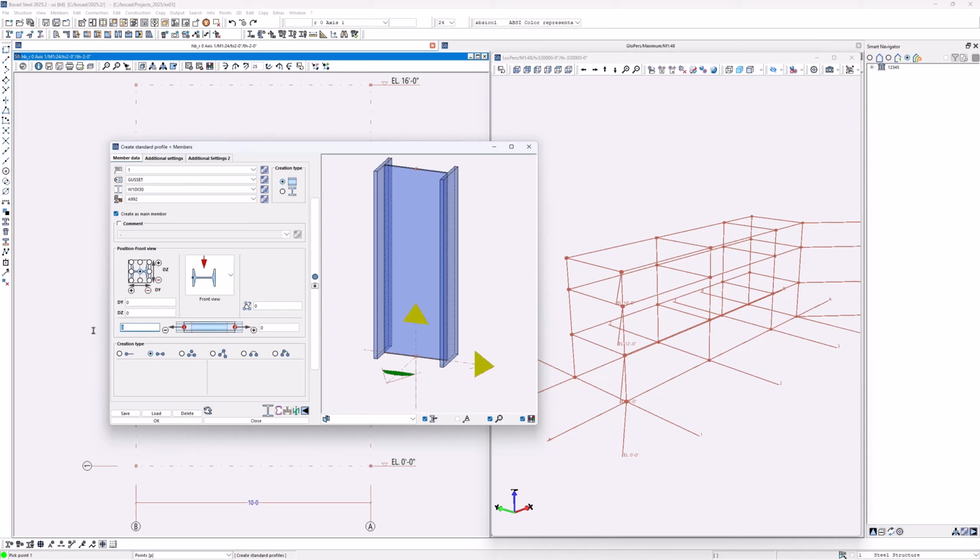And finally, you could add a little extension. So let's say we want to extend this profile maybe by 5 inches at the start point, or retract it by 1 inch, make it 1 inch shorter. It's not really that visible. Let's make it minus 5 inches, for example. You can see it better. So it gives a 5-inch offset from the starting point, and we can also enter a similar offset at the end point. That will avoid you having to lengthen or shorten and adapt something afterwards.